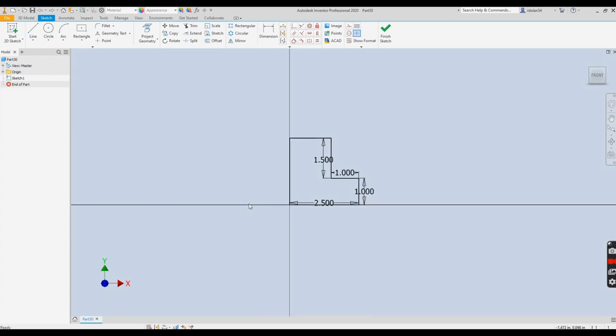And now we're going to take a look at the mirror command. The mirror command does just that. It makes a mirror image of what we pick, and it will copy it or move it at the same time. So I'm going to go to mirror. You'll see that's basically the same thing, with only a couple of different things. It has a select, so I select everything here. Now it needs a mirror line. I have to mirror it around a line. I can't pick the origin or a spot. I need to have a line to mirror it around.